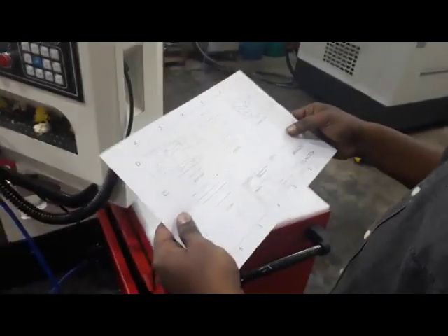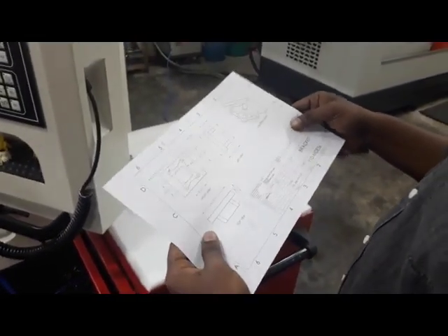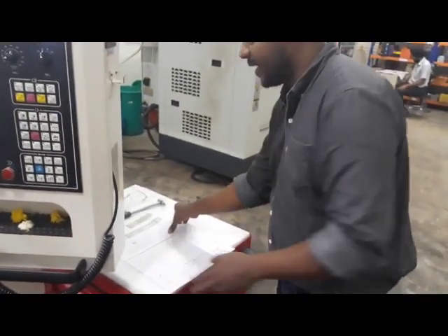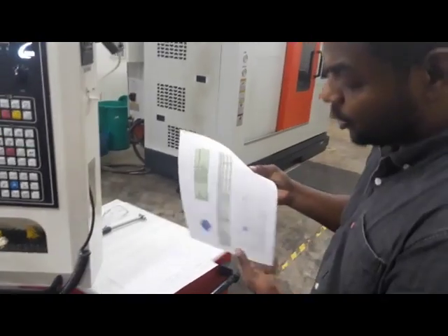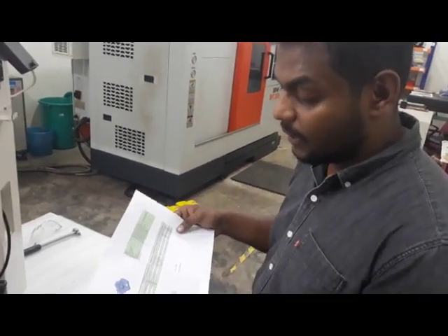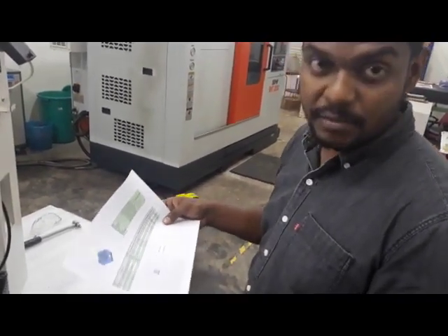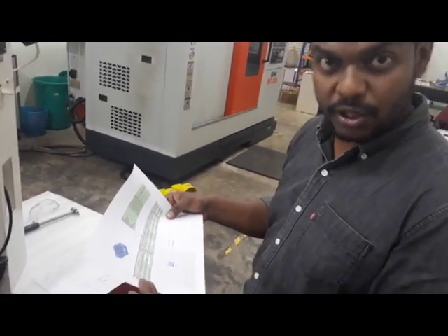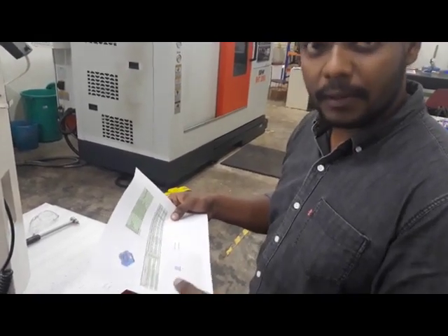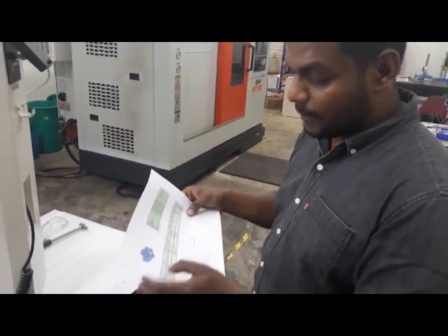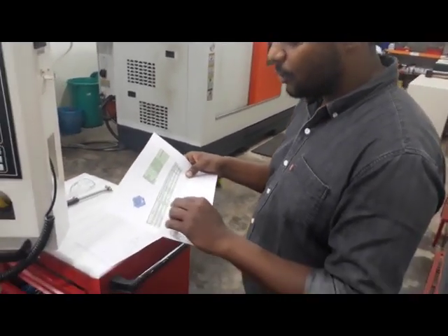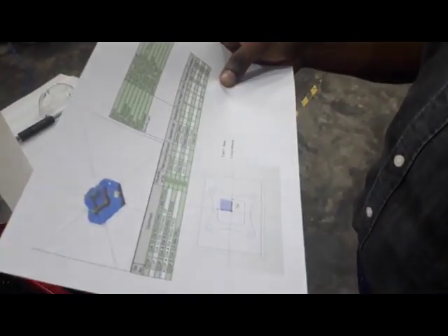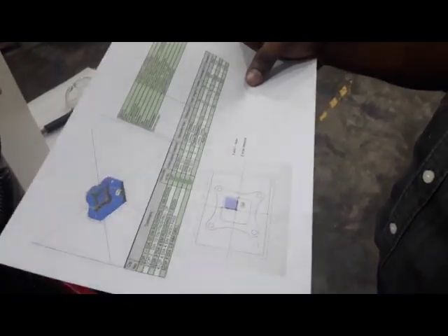This is the engineering drawing that I showed you before. Based on this, I had explained to you that I had created a process sheet. This process sheet is something that an operator, a CNC machinist, goes through, and it's like a checklist for him to understand what the operations are in this particular machining process, the work offset that he needs to understand, and the step over, the step downs, the tool diameter, the feeds and speeds that he needs to be aware of.